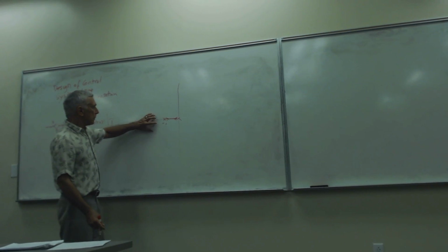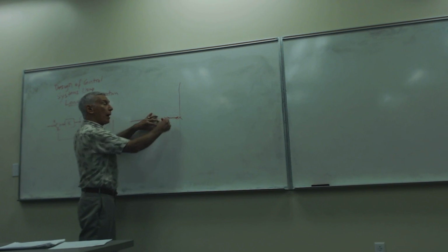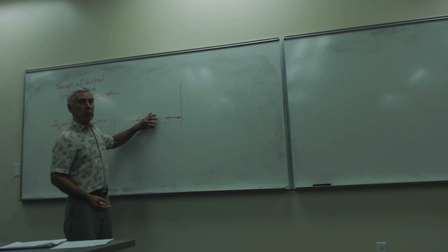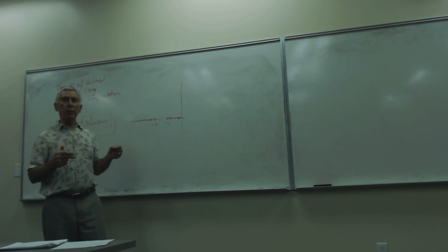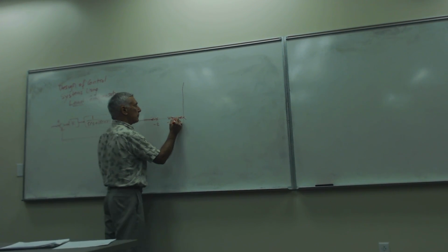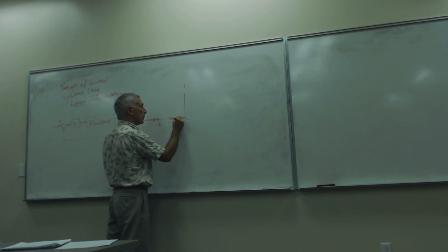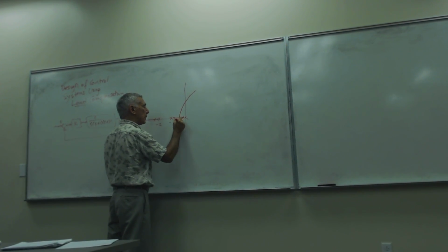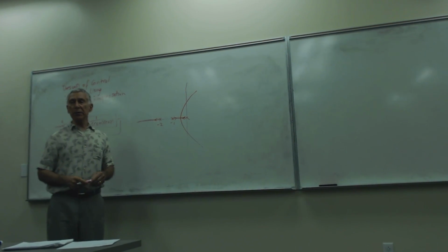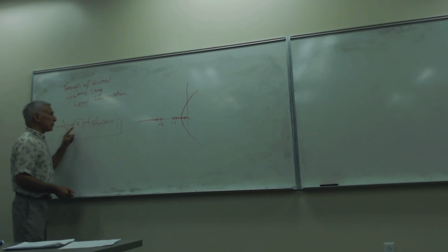If you didn't have that pole there, it would just break away and go vertically up and down in the middle at -0.5. But the pole will basically repel the root locus. So in fact the breakaway point will be somewhere to the right of the middle, and it will go unstable eventually as the gain K increases. And so that's using pure gain compensation.